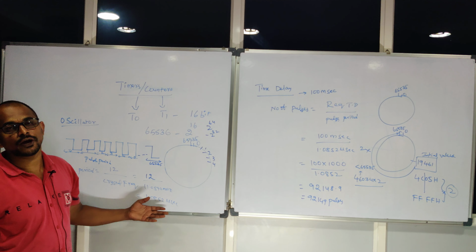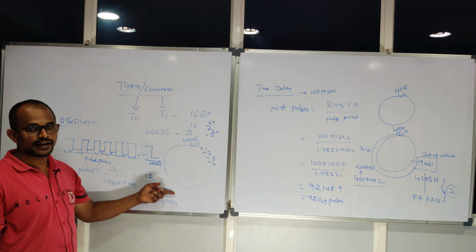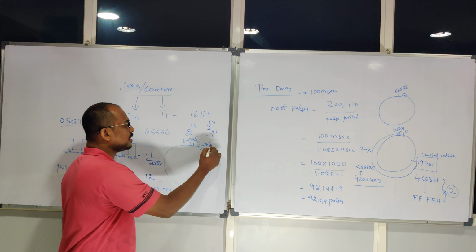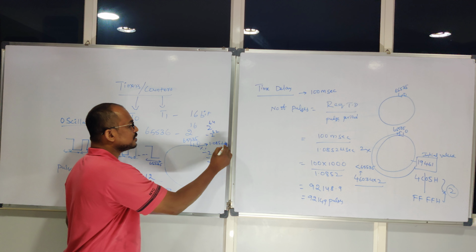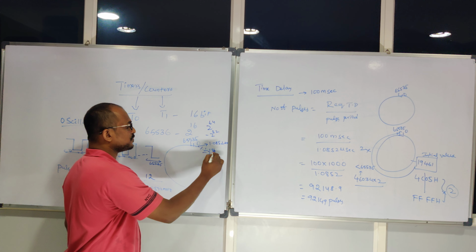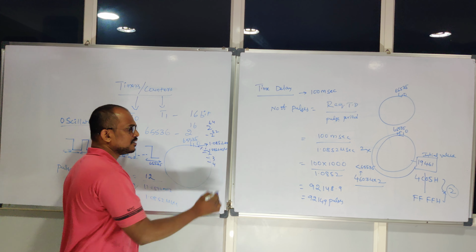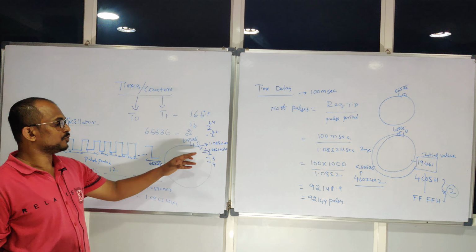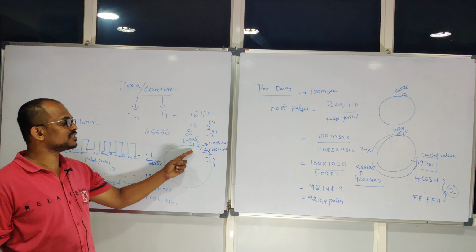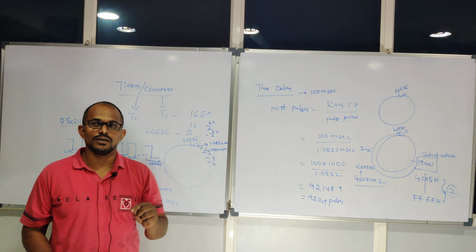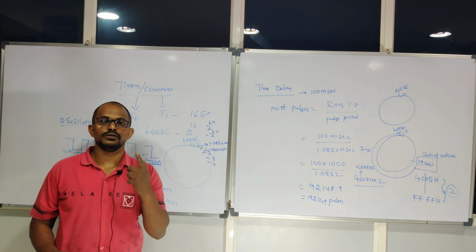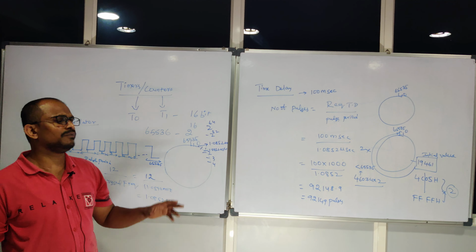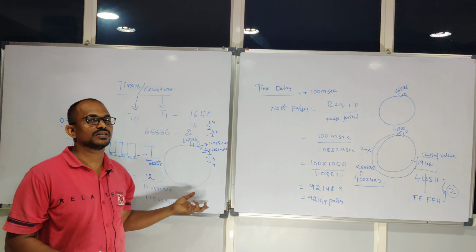So as per this, 12 divided by 11.0592, I'll get 1 point something, and since it is in megahertz, it becomes microseconds. Which means if I count 0 to 1, the time period I am getting here is 1.0852 microseconds. This is fixed, which cannot change from count to count, from pulse to pulse. For each and every count it gives a fixed time for us, like our seconds needle counts one count, the exact time period is 1 second, which does not vary from count to count, right? The same way your timer is also doing the same functionality here.